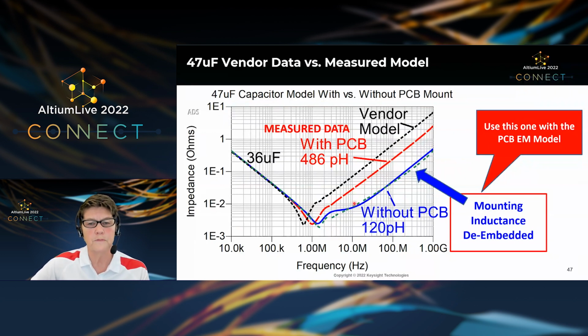Well, first of all, I would say, as a power integrity engineer, you really do need to learn that skill. You need to be able to measure what you're buying and verify that you're really getting the performance that you think you're getting from those capacitors. You also need to be able to verify that your design is working the way you expect. So being able to do these two-port shunt impedance measurements is a very valuable skill to have.